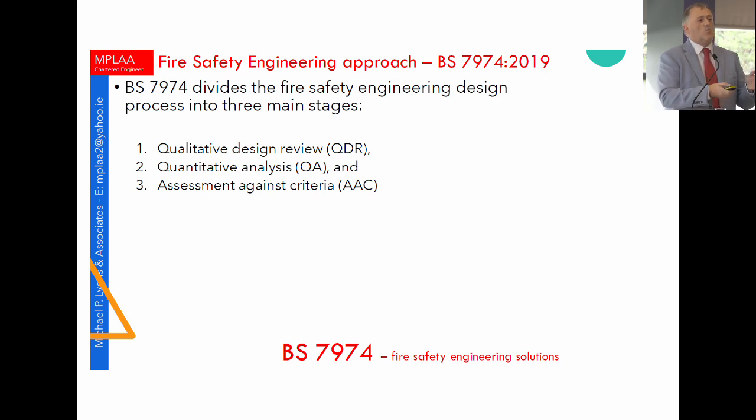You've got to show when the fire starts in the various different scenarios, and you've got to choose your scenarios correctly, because those scenarios ultimately have to be presented to the assessing officer, who's got to accept that they reflect the likely fires that will occur in your premises that will put the fire safety strategy to the test.